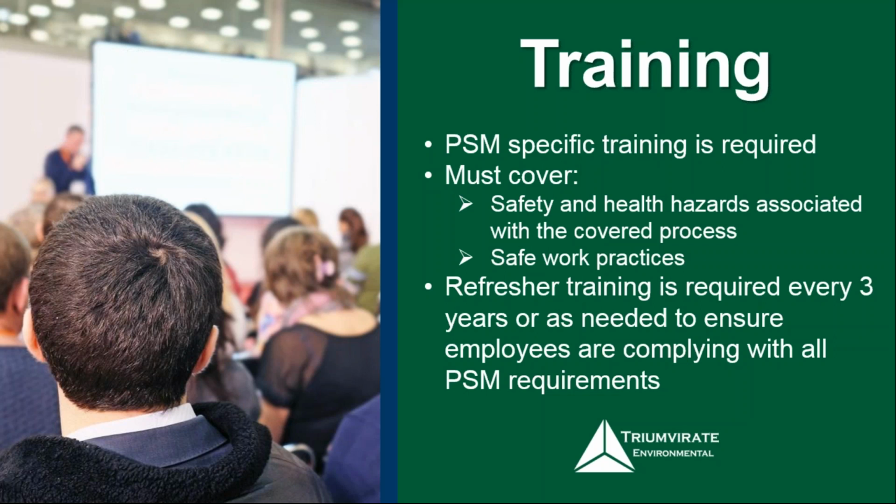Well, I say you do, but you're doing that under different regulations, right? So you might be doing that under HAZCOM or emergency action planning or something like that. This is specific to say, okay, we need to make you aware we have a PSM regulated process here at this facility. We have it for this chemical. This is why it's for that material, which is around, again, back to the toxicity, and we did a process hazard analysis. And if, God forbid, something went wrong, this could happen, and we need to make you aware of it so that this is all rolling together and everybody knows about it.